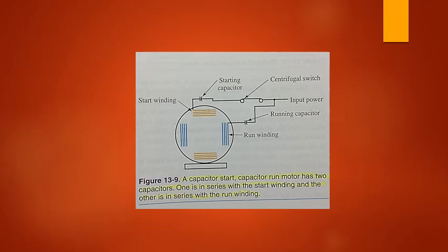When the motor reaches about 75% of its speed, a centrifugal shorting ring shorts out all of the commutator sections. The motor runs as an induction motor. The repulsion motor has high starting torque, but it does not quickly come up to speed under load. It is currently being replaced by less costly capacitor start motors.